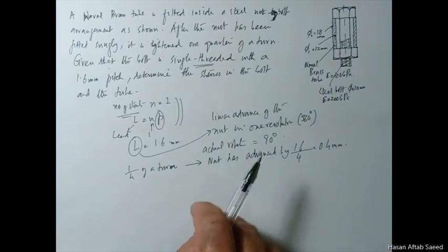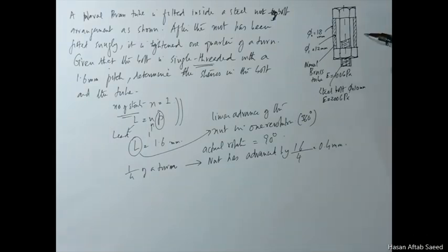So we don't know yet how much the steel bar extends and how much the tube shrinks as a result of this turning of the nut. But we know one thing for sure, and that is the combination of extension of the bolt and contraction in the tube is equal to 0.4,